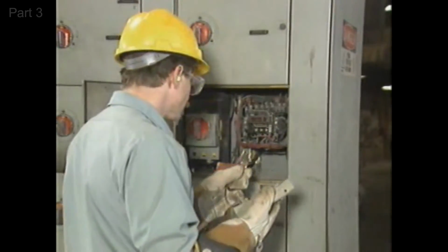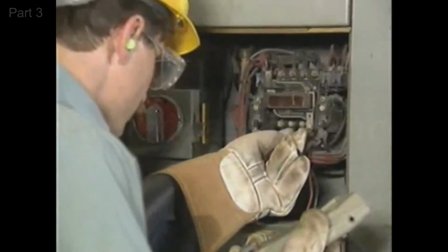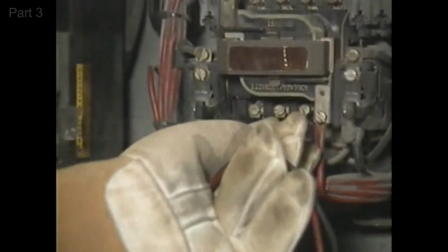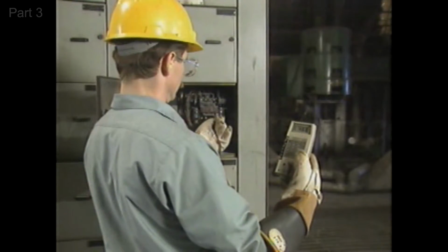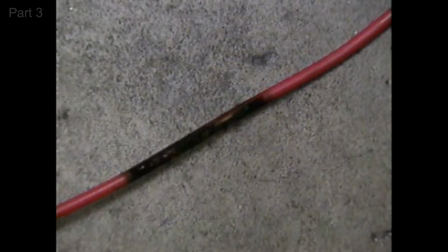In a case like this, an electrician may first attempt to locate the problem by testing the malfunctioning controller while it is energized. It's important to remember that you should test an energized controller only if the symptoms of the malfunction indicate that testing will not further complicate the controller's problem. For example, symptoms such as the smell of burnt insulation, sparks, smoke, or glowing wires are warning signals that you should not test the controller while it's energized.